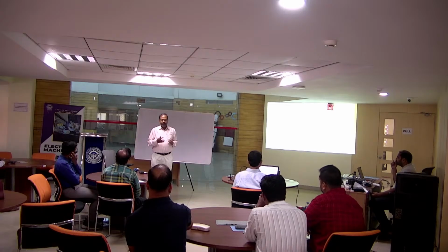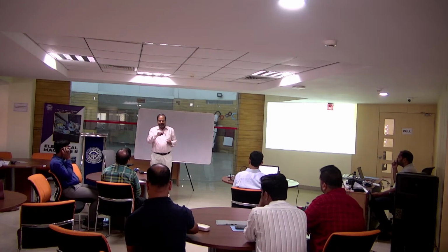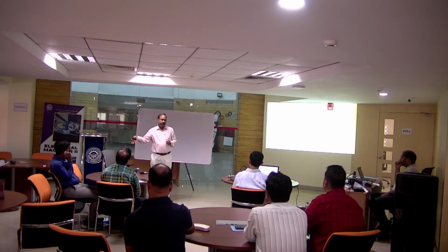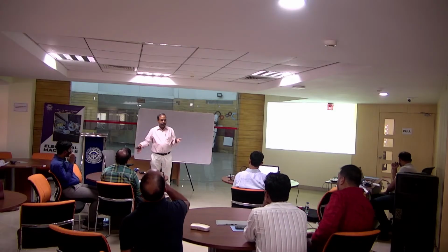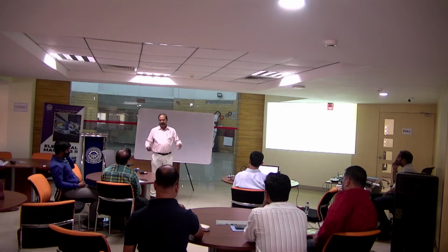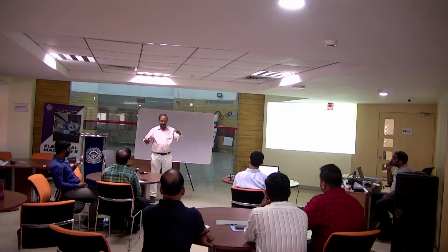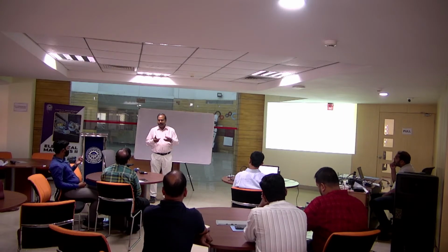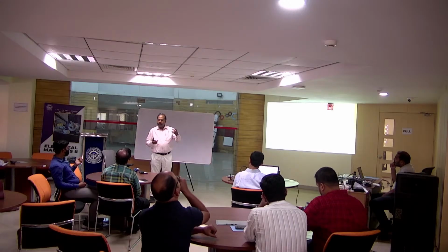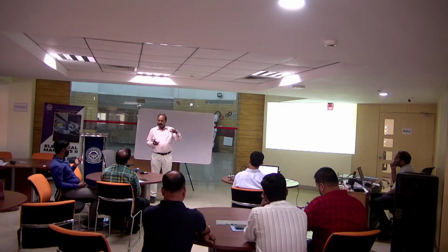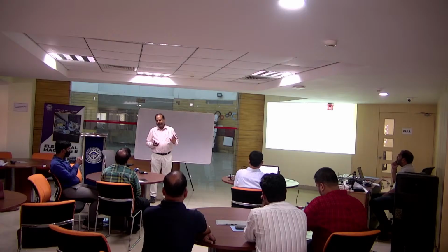And the rotor terminals are there, slip ring induction motor. That rotor terminals you take and feed to another induction motor starter. So you get different speed operation. And this is cascade connection, and they are coupled on the same shaft. So the resultant torque will be the sum of the torques or the difference of the torques.